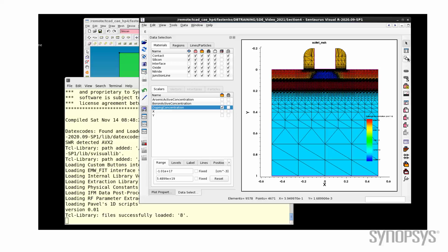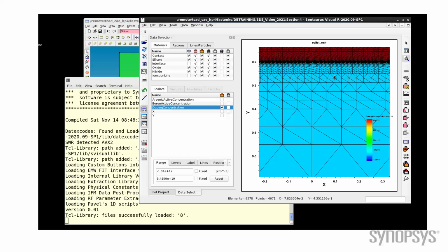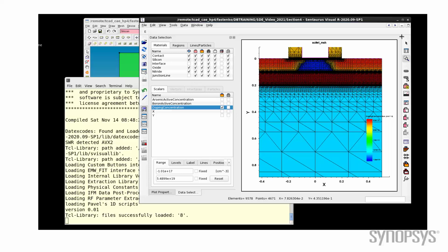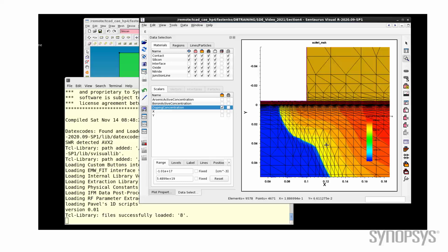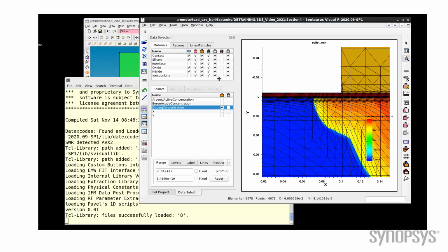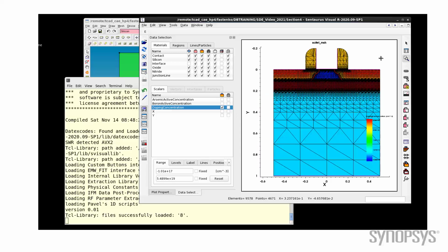Let's examine the structure. Mesh is anisotropic with global refinement, ensuring reasonable refinement in the substrate, in the box layer and substrate box interface refinement. The second refinement definition controls the mesh near the junctions and in the channel of the device.